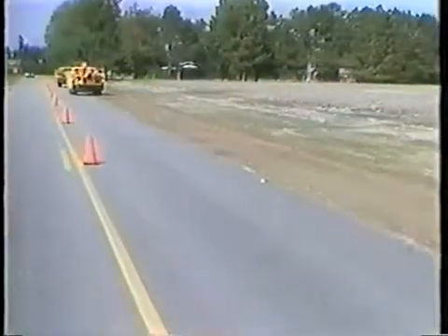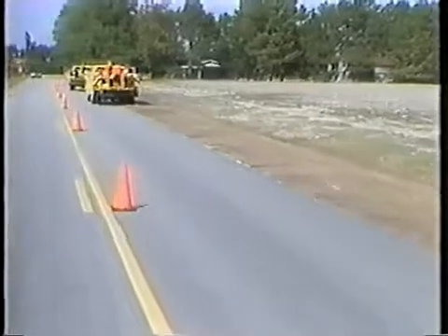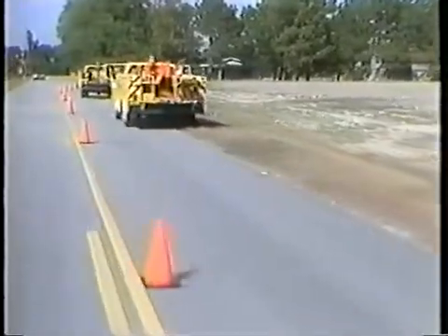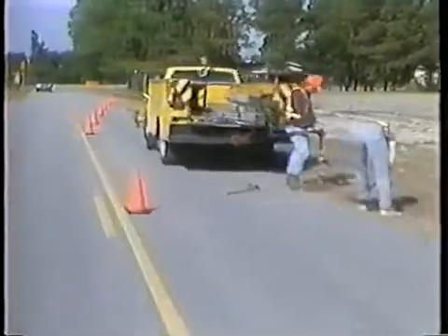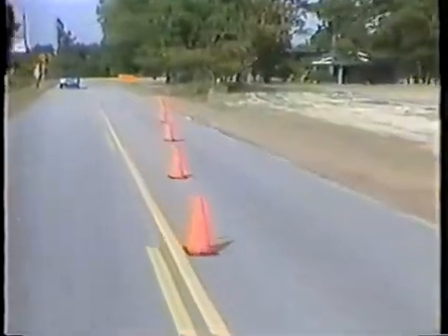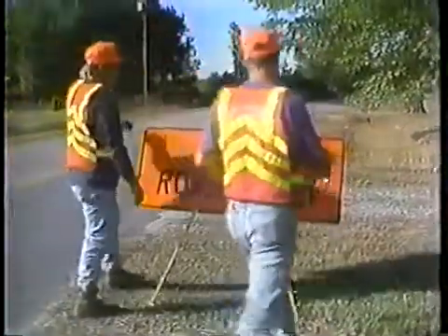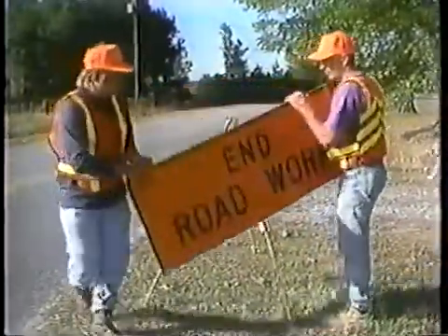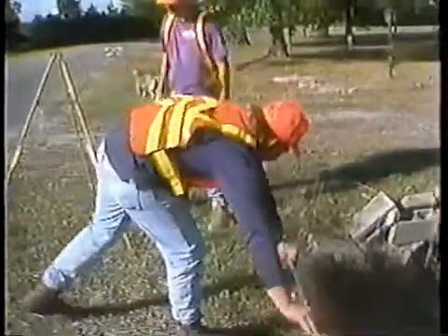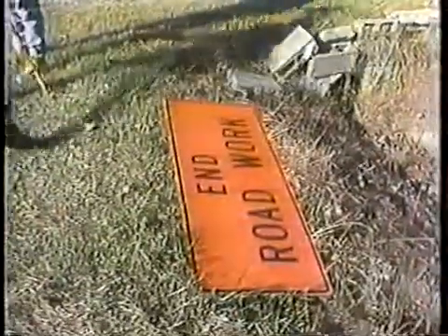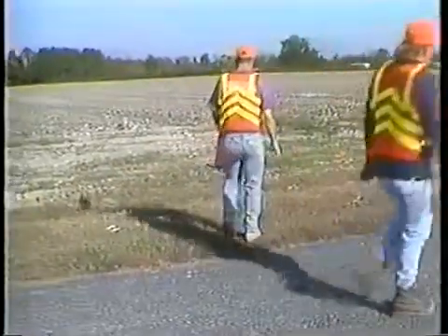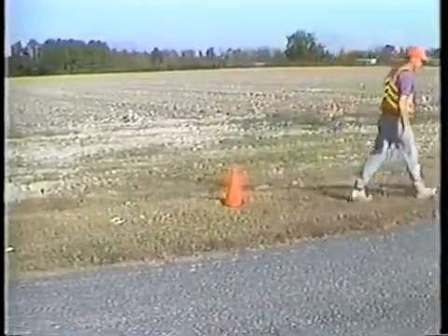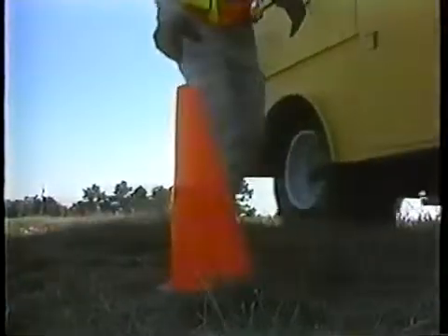As previously emphasized, the best way to evaluate traffic control is to drive through the work zone after all the devices are in place. Now the work activity may begin. After the project is completed and all workers, materials, and equipment are off the roadway, the traffic control devices are removed in reverse order of installation. Remember, a good technique for removing the devices is to first place them on the shoulder of the roadway, then pick them up in the direction of traffic flow.